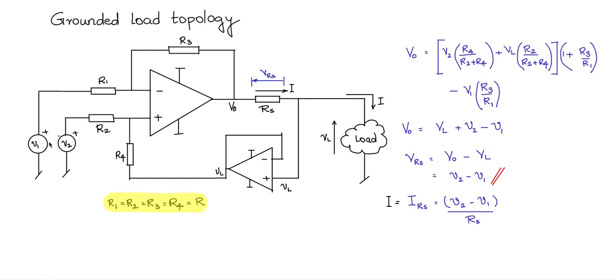If you want to give an offset, for example, you want to give a current here of 4 milliamps when V2 is 0, you can use this as your zeroing circuit or offset adjust circuit. So you could have a negative value of voltage here, and because this will again invert because of the minus sign, you will get a positive voltage drop across this when V2 is equal to 0, and by RS we can set it to 4 milliamps.